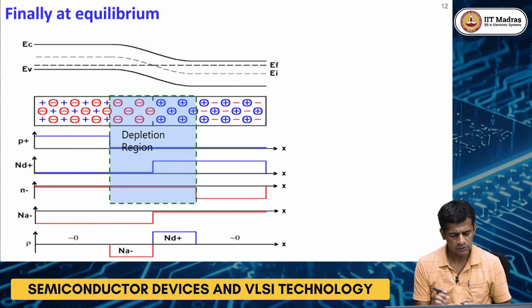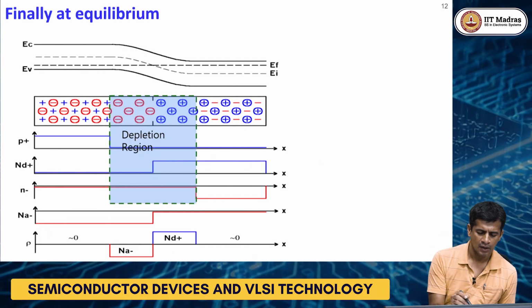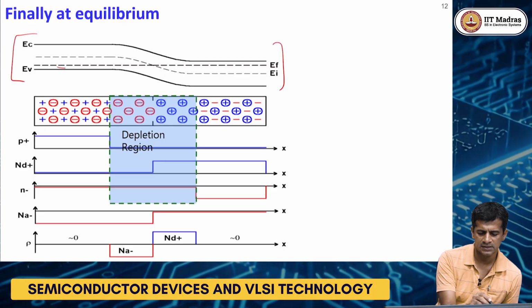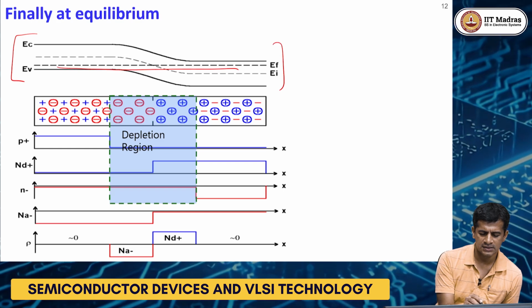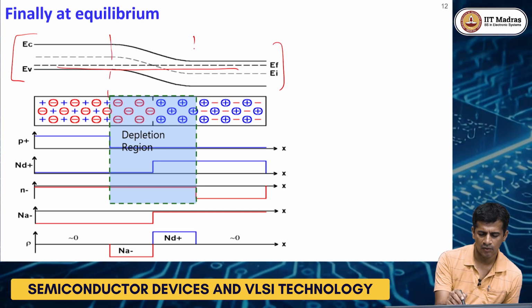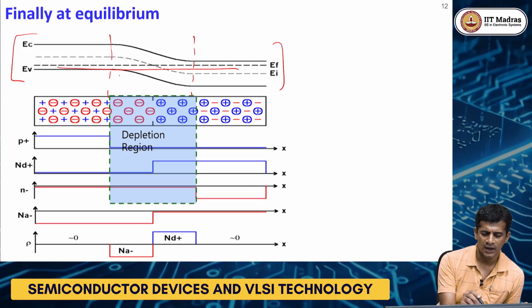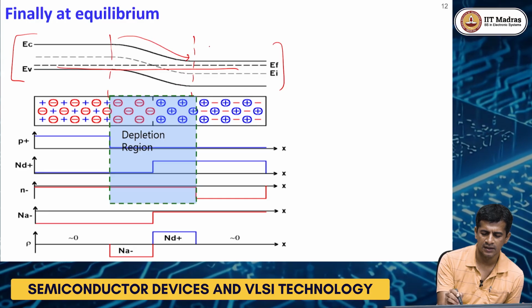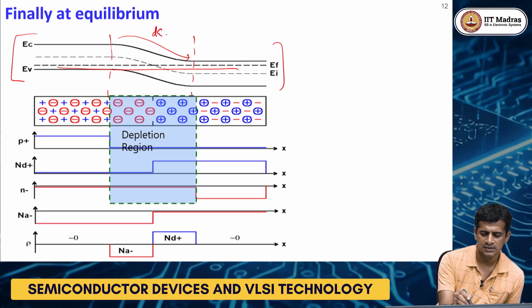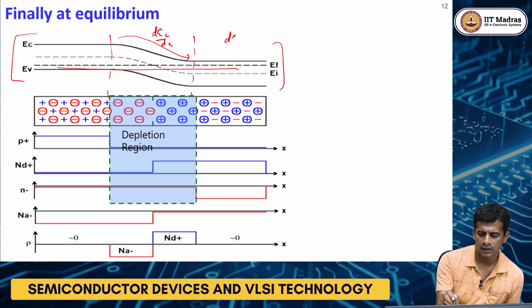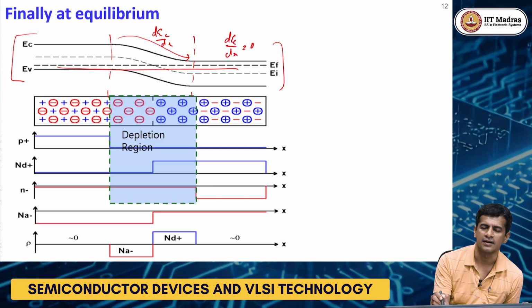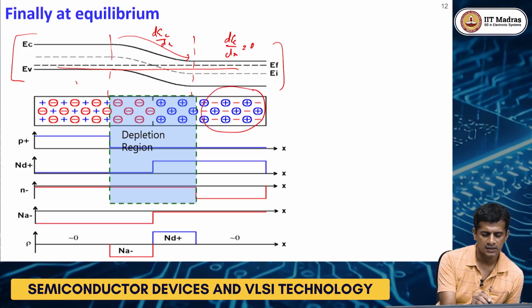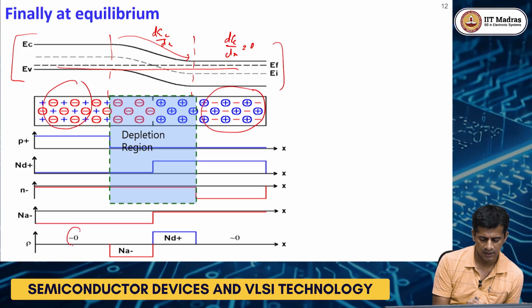So this is the energy band diagram under equilibrium. The Fermi level is continuous, and you see some region here. In this region is where you have electric field, because this is where the band bending is. Here dE_C/dx is equal to 0, this is flat. Flat means it is quasi neutral. So this region is electrically neutral, and this region is also electrically neutral.